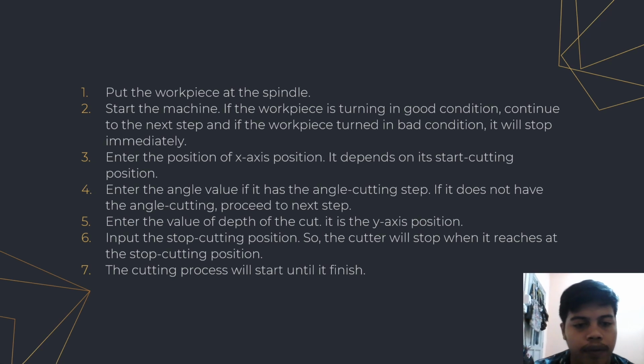If it does not have the angle cutting, proceed to the next step. Fifth, enter the value of depth of the cut, which is the depth is y-axis position. Sixth, enter the stop cutting position, so the cutter will stop when it reaches the stop cutting position. Lastly, the cutting process will start until it finishes.